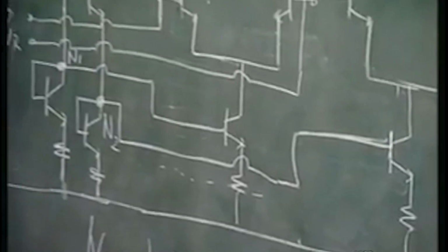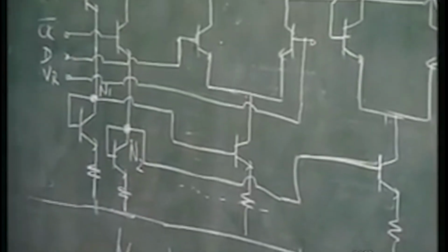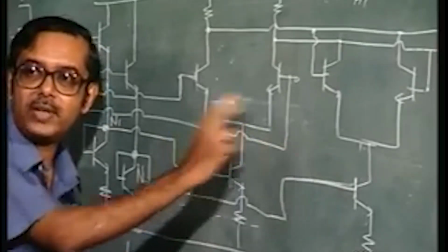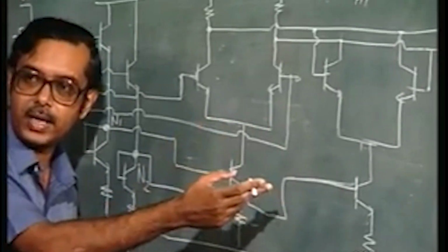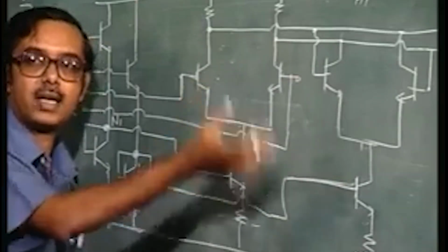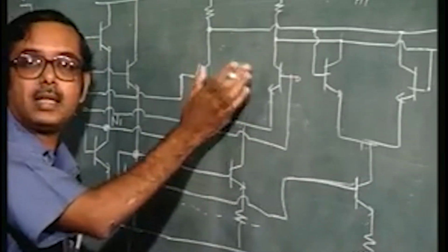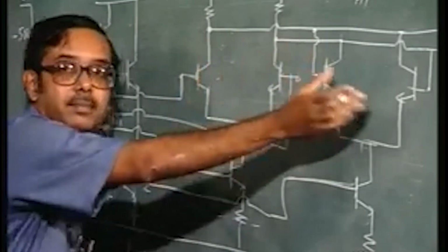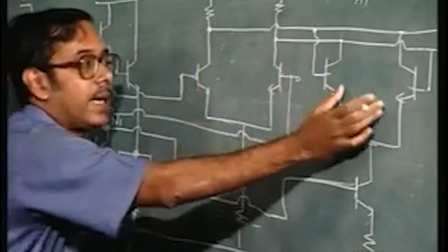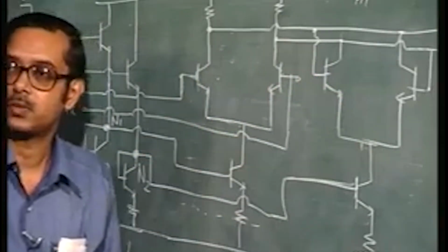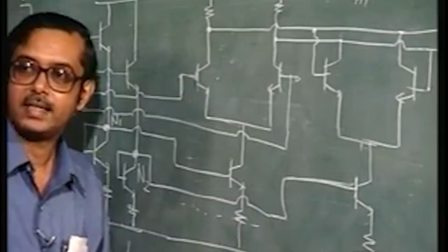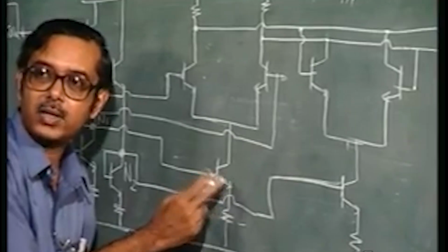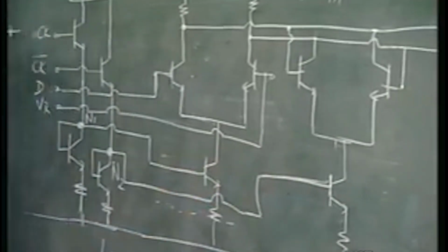So basically what we want to say is, in the previous circuit you had an emitter coupled system here, to which you are feeding the clock and clock bar, and depending on whether the clock is high or clock bar is high, either the left part or the right hand side stack emitter coupled structure in the upper stack was on. Here, instead of an emitter coupled structure at the lower part of the stack, you have an arrangement like this.